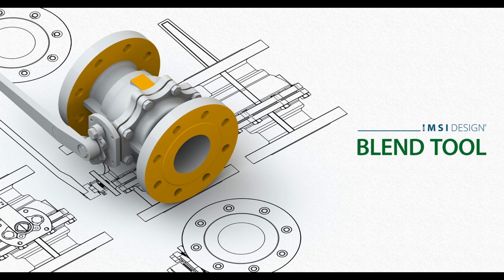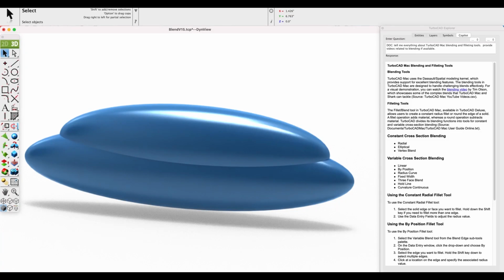Blend tool. The Blend tool has the ability to assign a version to use for filleting and blending calculations. Blending uses the ACIS modeling kernel, which is constantly evolving its algorithms. In some specific cases, older algorithms may provide better results. In order for the designer to have more control, there's now an option to use the current or version 10 blending algorithms. In this example, we have a complex fillet that requires version 10.